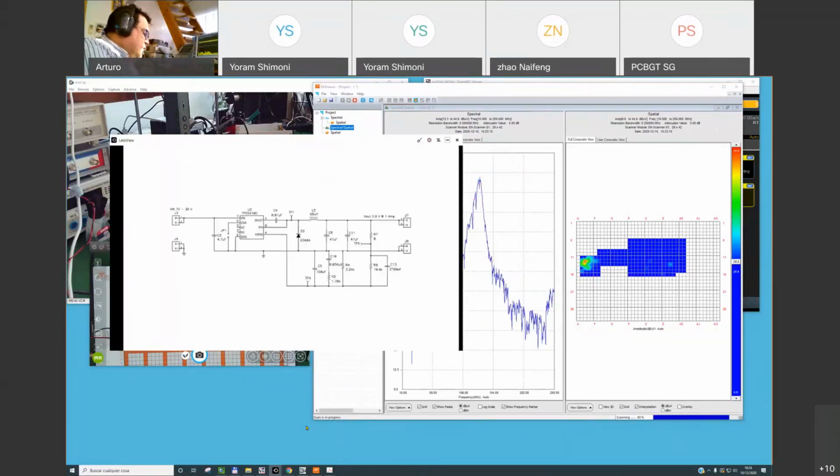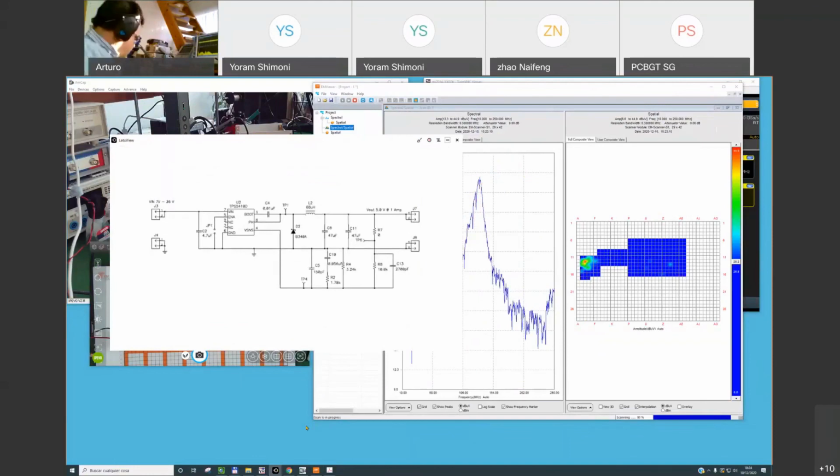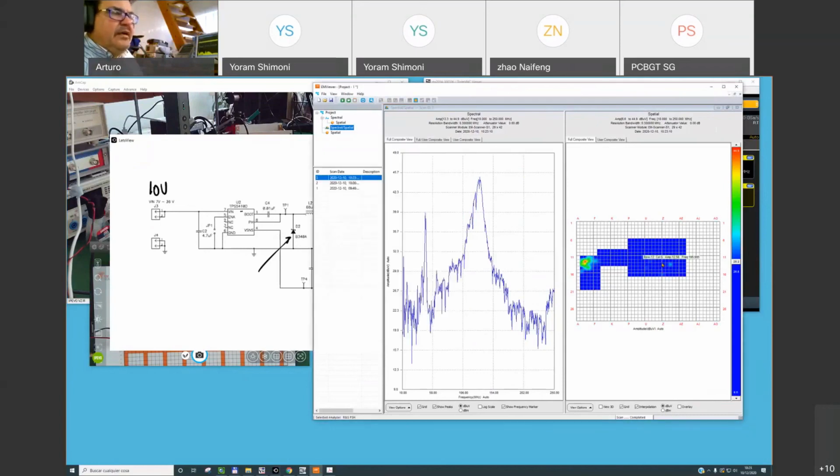This is my DC-DC converter, where I am going into the circuit with around 9 volts, 10 volts here. And you can see this is the TPS5410D. We have one inductor and we have the diode here to go out with 5 volts. Okay, this is the area of interest.